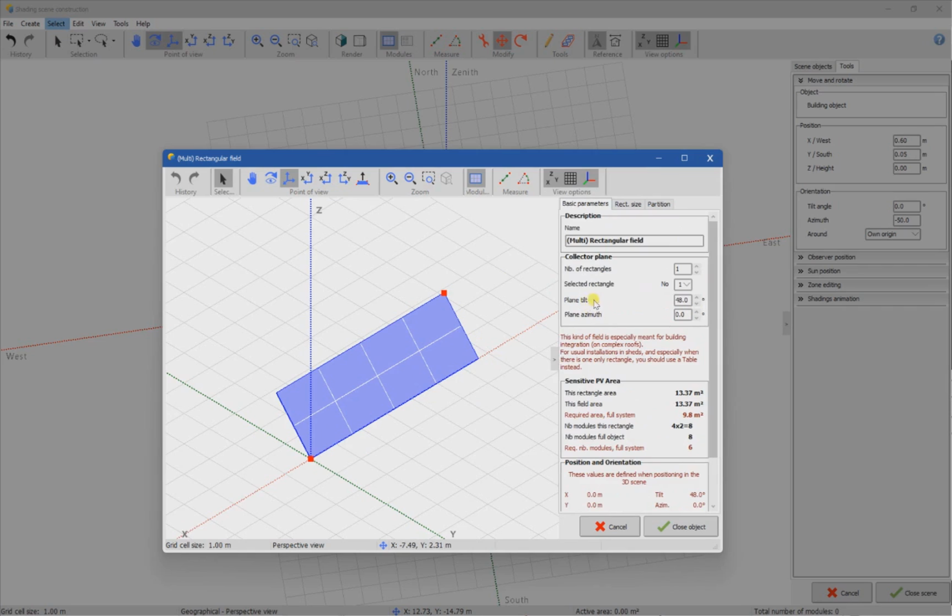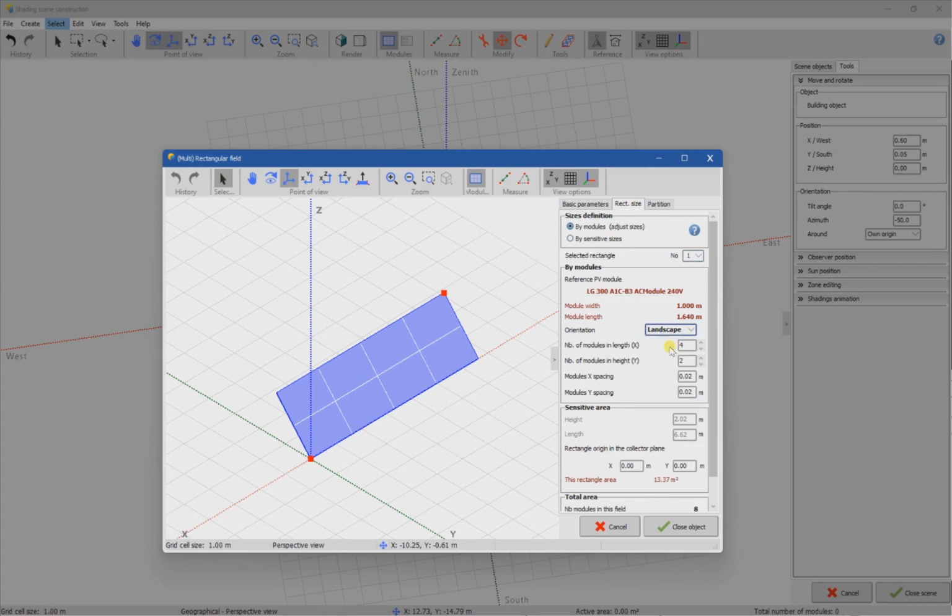So the first step is that we will go here. You will see tilt angle and azimuth. We will exactly have control in them. If you remember, we have control on them from what we have learned. And if I would like to change their size, remember that these panels will be on one row and other panels will be another row. So I will divide the 2 strings into 2 rows. One row for a string and another row for a string. So each row has 3 panels, right? So I'm going to choose here 3 panels like this.